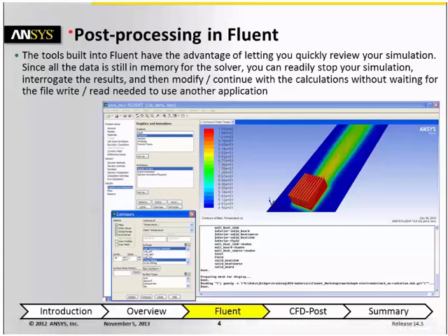We will start first by talking about post-processing in Fluent. The tools built into Fluent have the advantage of letting you quickly review the simulation. Because all of the data is still in memory of the solver, it's easy to stop the simulation and check the results, and then you can either modify something in the case setup or continue with the calculations, and all